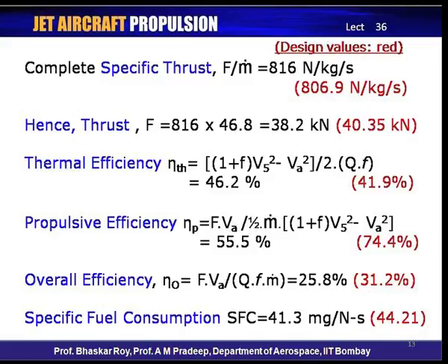Now, this higher thermal efficiency also stands to reason by the fact that at off design it is operating at higher pressure ratio. This higher pressure ratio indeed yields the higher thermal efficiency, and we had seen that it also gives higher specific thrust. So, we have an off design operating condition now, where certain parameters are indeed higher than the design point parameter, in terms of compression ratio, in terms of specific thrust. However, the mass flow is lower, and the thrust produced is lower. Indeed, it is supposed to be flying at a lower Mach number.